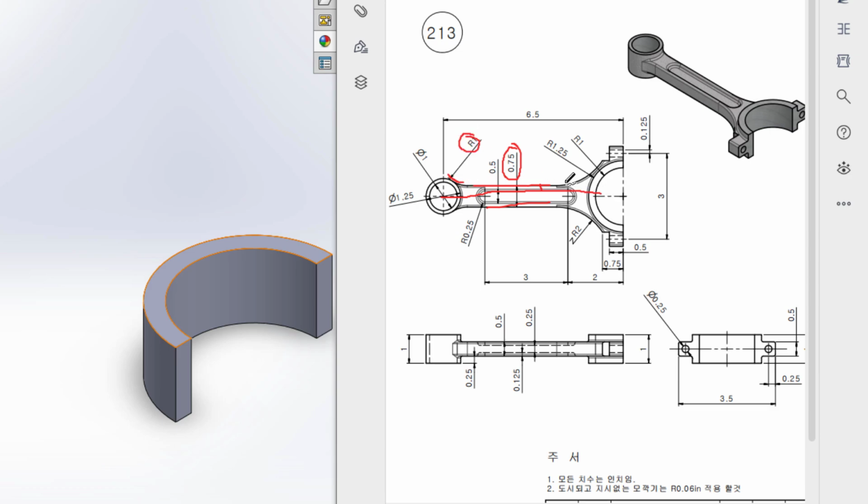Then I can see we have another fillet here, and this fillet has a radius of 1 unit, and we can see another fillet here, and this fillet has a radius of 2 unit. For drawing this 2 unit radius fillet, we have to draw this extra portion, and you can see that in our sketch the total distance from this point to this point is 3.5 unit.